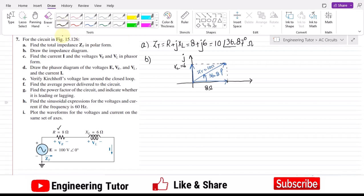Now in part C, find the current I and the voltages VR, VL in phasor form. So in part C, I have to find the value of current. I have also found the value of the total impedance, so finding the total current here is very easy, because the total impedance is also known. So it will be E divided by Zt. The value of E is known, and that is 100 volts with the angle of 0 degrees.